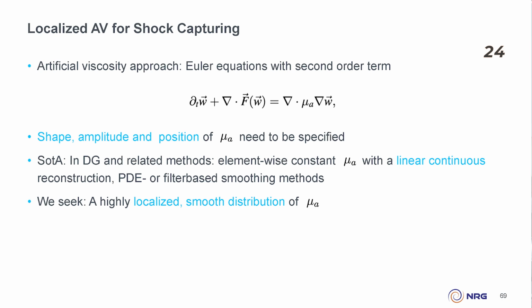So the orange and the blue and green ones, they are what we came up with. The only difference is how we target the artificial viscosity, and you can see clearly that on the same grid, everything else being equal, our approach is much better at not smearing out the gradients too much. And when we look at why this is happening, at the artificial viscosity fields we used here, you can see that they are much more targeted, right? They are much more narrow than the ones that were the current state of the art a couple of years ago. So this is a much more targeted application of the shock capture mechanism, making use of the information that we got from machine learning. Okay, some examples that this actually works in practice as well.